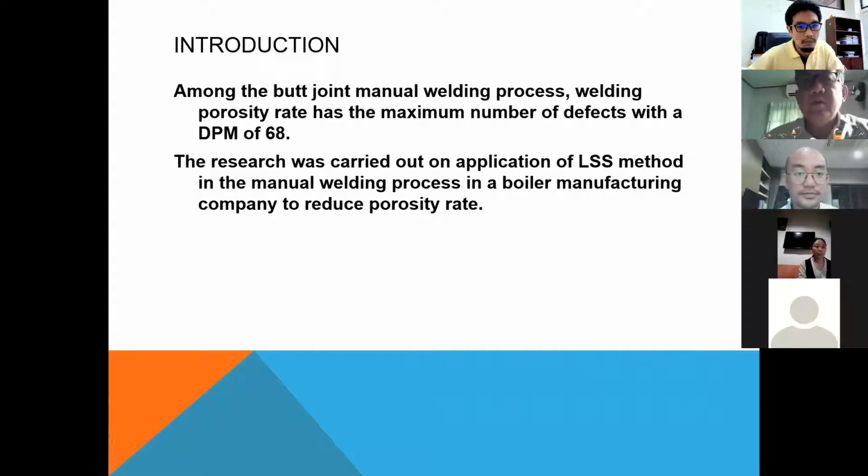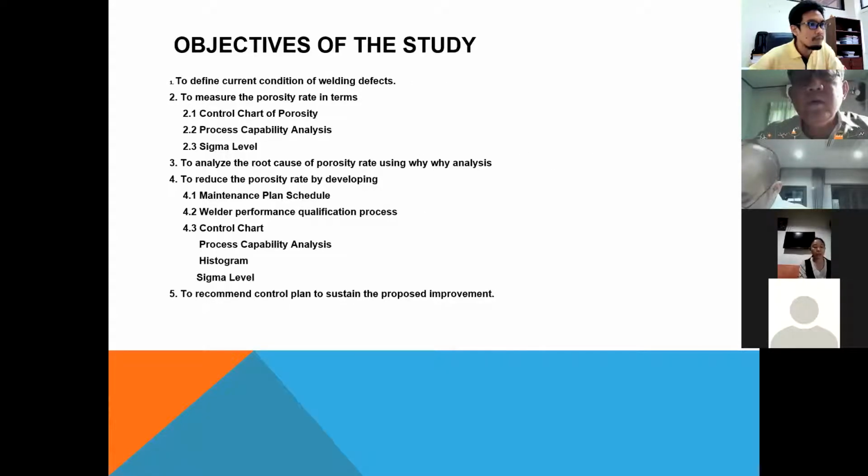Okay. So the welding defects: porosity, lack of fusion, undercut, excess penetration, concavity, offset, filler, incomplete penetration, and tungsten inclusion. By using Lean Six Sigma technique, the defect was minimized and product excellence was confirmed. The target weld porosity rate that needs to be reduced was 33%.